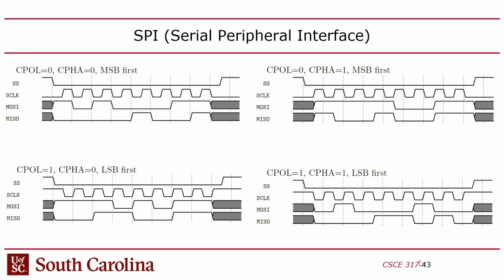CPOL was the polarity of the clock, what the clock is when the bus is inactive, and CPHA was the clock edge versus SS and data.